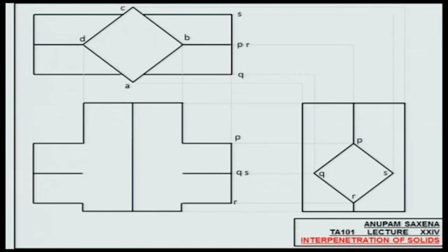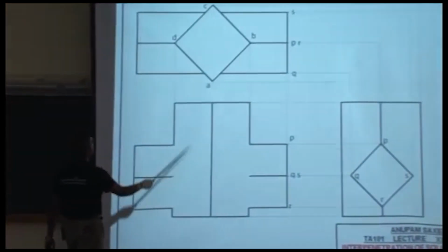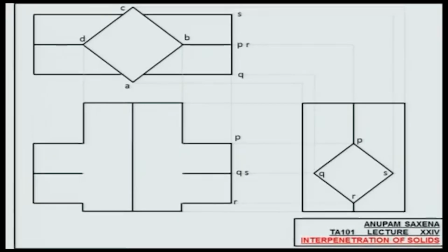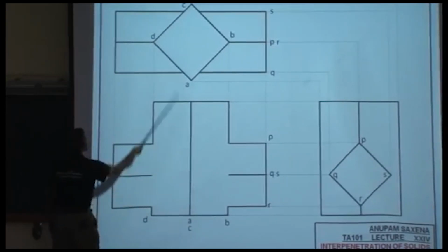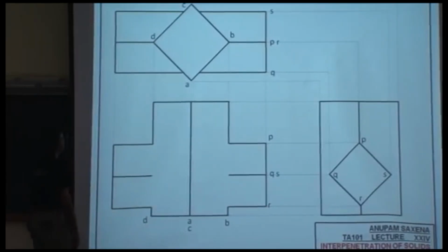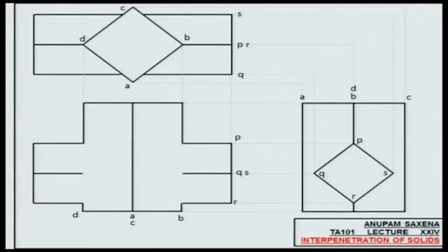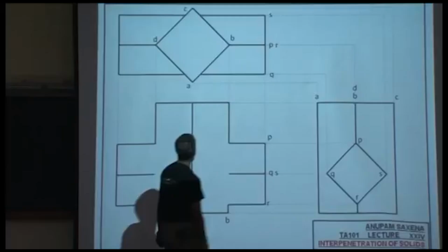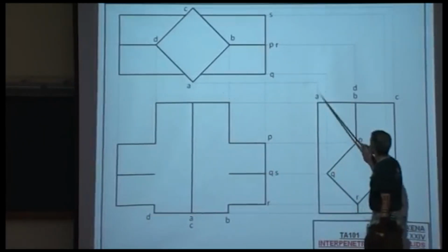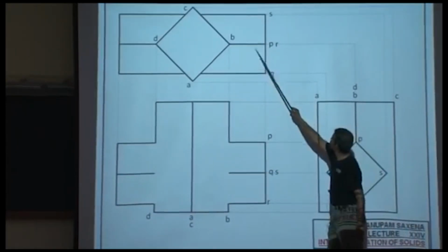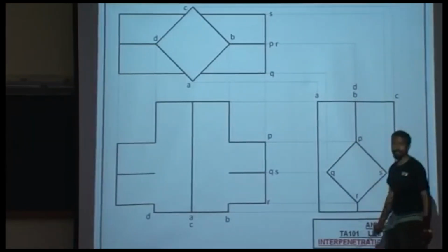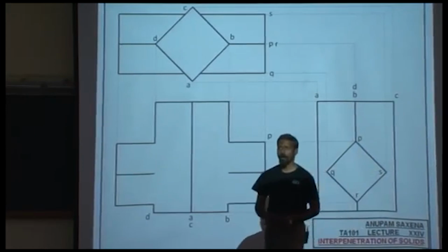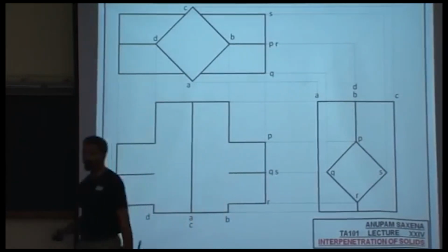Label the vertical prism in the front view. So A, B, C, D. Okay, so this is A, B, back side or the back edge C, and D. And likewise over here, A comes from here, B comes from here, the center, C comes from the top over here, and D again at the center. Step 1, you have to do labeling properly. Okay.